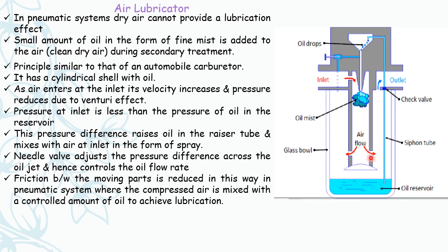In order to adjust the pressure difference across the oil jet, this needle valve is present and hence controls the oil flow rate.